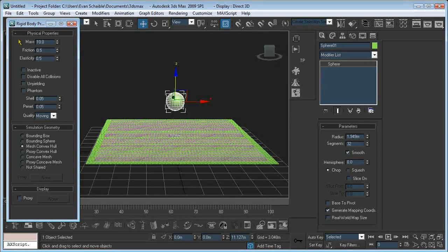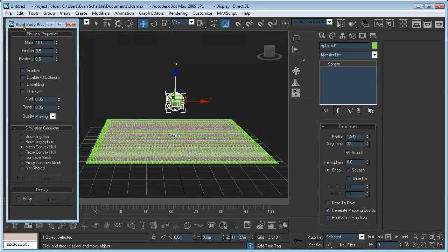Now, within the Havok system, physically accurate settings are usually between 0.1 and 1. If you go out of that range of settings, you'll get warnings from Havok that tell you you'll get physically inaccurate and unrealistic results from your animation. Unless you're going for a specific effect, it's not usually beneficial to go outside of that range. But for this demonstration, we're going outside of that range, and we'll probably be outside of it for the most part.